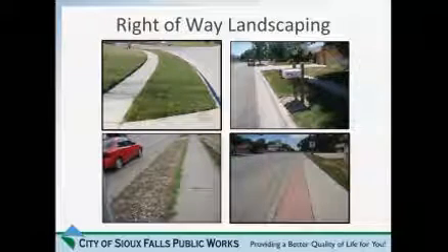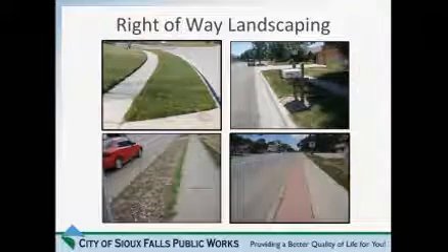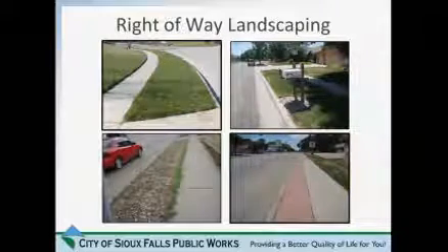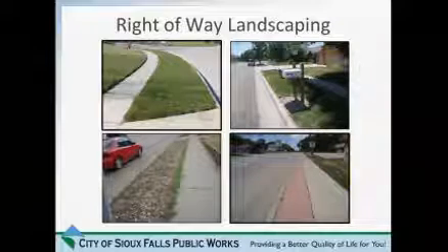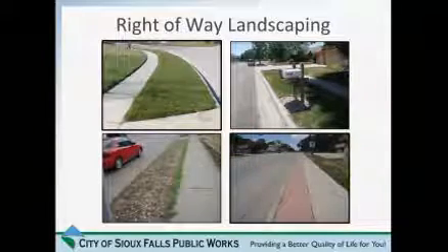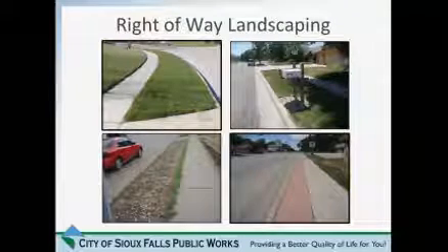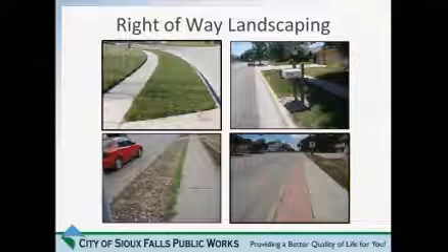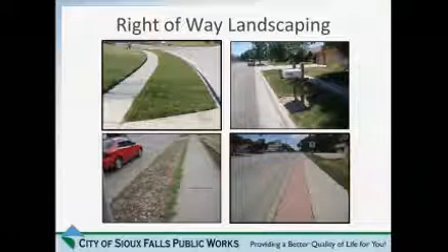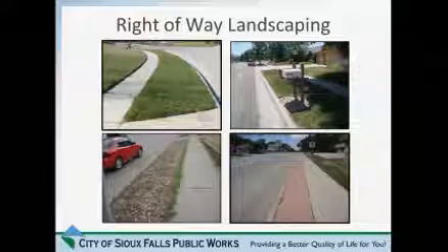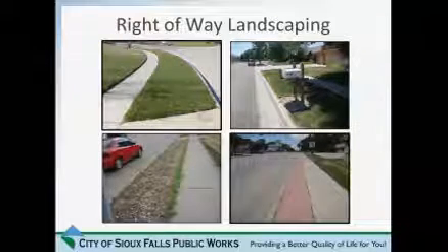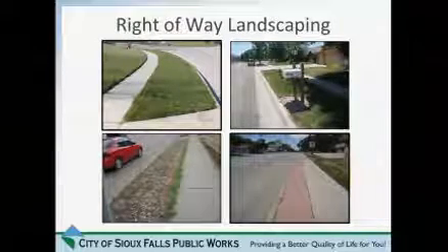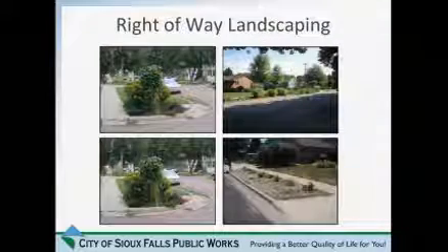On the bottom right, it's a picture of what I like to refer to as splash guards. On some of our high-volume streets, especially during snow removal operations, it can be difficult to maintain a small boulevard with some of the chemicals that are put down. It makes keeping grass growing a challenge. So we thought we would clarify some of the options for the public, and on those high-volume streets more formally allow splash guards like the concrete infill I'm showing here. That's a quick overview of part of the right-of-way landscaping.